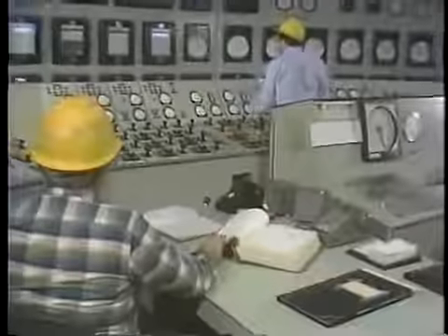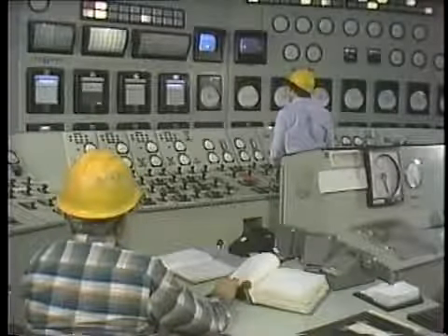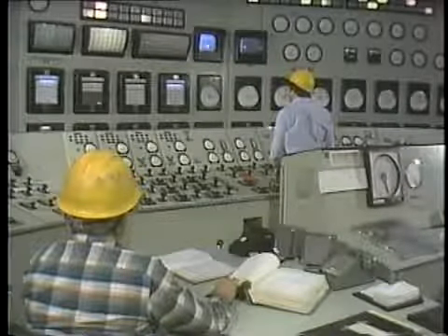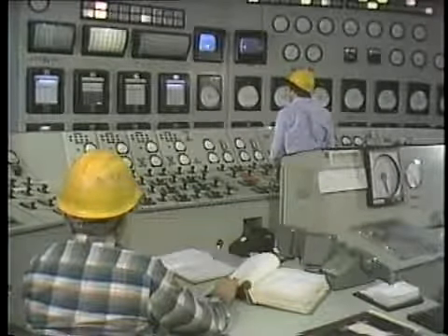Now, the chances are extremely good that if you follow your plant's operating procedures and monitor your equipment properly, your boiler is not going to explode. However, by understanding why boilers explode and the situations that have the potential for causing explosions, you're better prepared to anticipate the possibility of an explosion and act to keep that explosion from occurring. In general, boiler explosions occur when an abnormally high concentration of combustibles is suddenly and uncontrollably ignited inside the boiler. Now, there are a number of situations that can lead to a high concentration of combustibles in the boiler furnace.